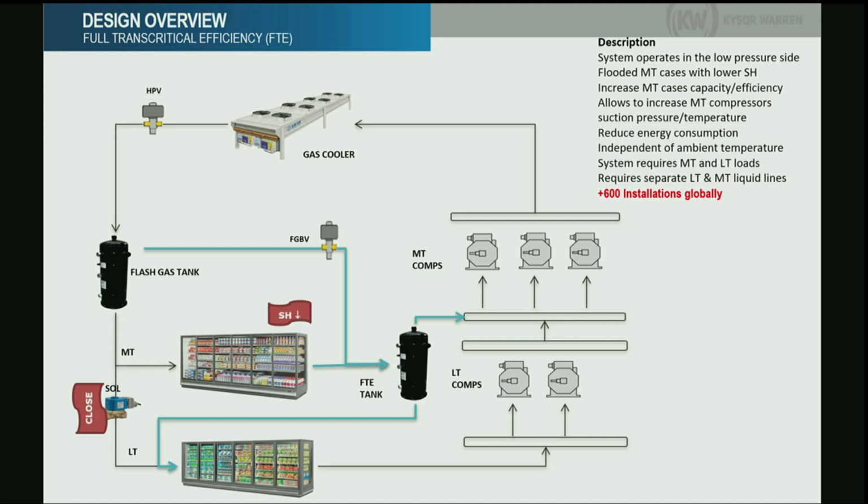This system, because all the operation here is at the flash tank or below, doesn't care about what happens on the gas cooler. It can be hot, it can be cold. This technology operates on the low pressure side, so it's completely independent of the ambient conditions. That's why Minneapolis is a good place to do this study, because it's cold. You don't get the benefits of the high ambient conditions. So, yeah.